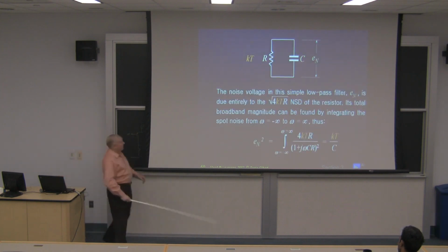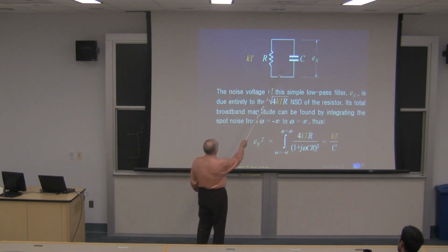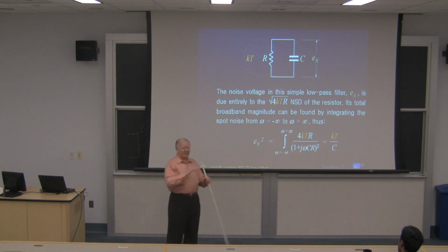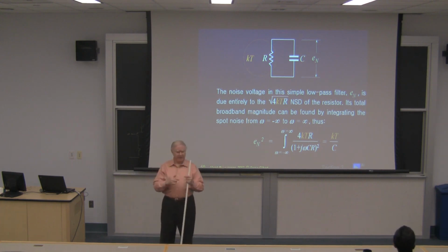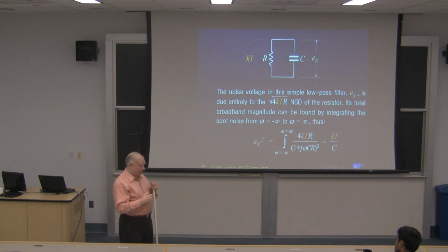Well, let's just take a simple RC circuit. It has its noise associated with KT. The capacitor over here is a non-dissipative element, so there's no consequence. Again, you can imagine this intuitively. Imagine two plates separated by a vacuum or by air. You can see, particularly in the case of a vacuum capacitor, that's the best example. Vacuum capacitors are used in transmitters, for example, because otherwise they might arc at high RF voltages. But if you imagine a vacuum capacitor, you can see there's no granular motion to talk about. There's nothing going on between the two plates.